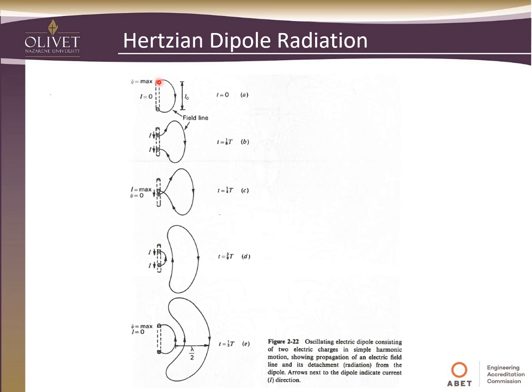Here's another look at that phenomenon. As you see, if we had that perfect dipole and we have those charges going back and forth, you can see they start to create this. It's almost like blowing a bubble, and some people even use that analogy, that this is an electromagnetic bubble now. If we had some source pushing it out, which would be our generator source back over here, this just repeats over and over and creates those waves and radiates them, and we can use that to transmit information, which is the big deal, right? Your cell phone, your Wi-Fi, all these things use these concepts, and this is how that works. And you have the tools to make those calculations and design different things for that.